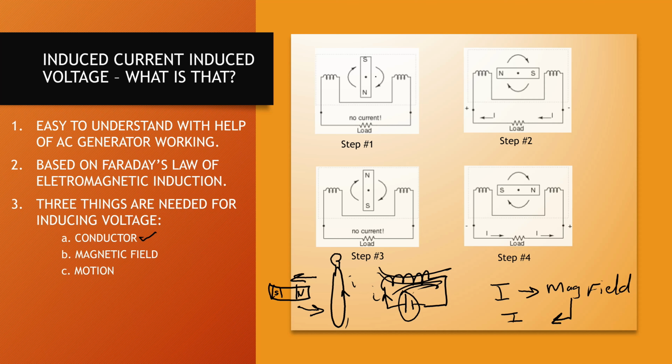See over here, you have this AC generator, you have your windings, and a shaft like this, and the magnet connected to this shaft keeps on rotating. As soon as the magnet is rotated, there is motion, which produces current in the coils, and it travels down through the wire. Whenever the poles change, the direction of the current changes.